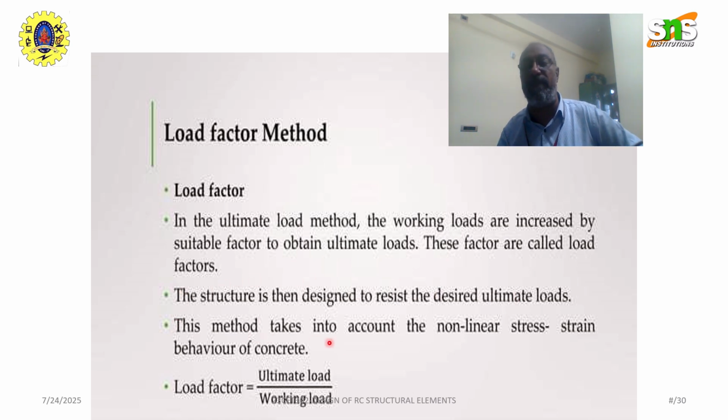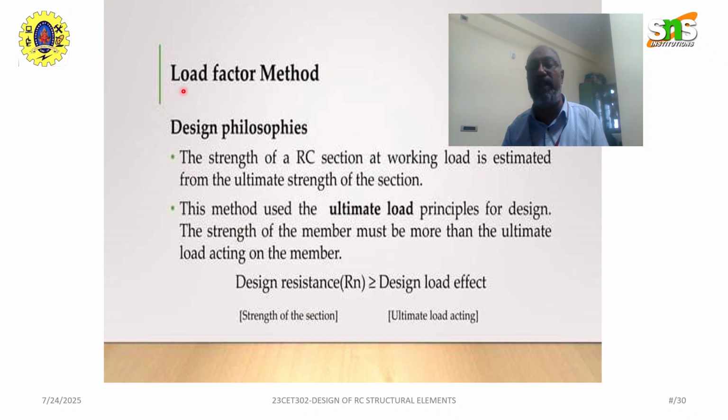The design philosophy is the strength of the section against the ultimate design loads. That means design resistance is greater than the design effect. That is the design philosophy of the load factor method.